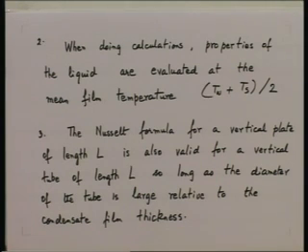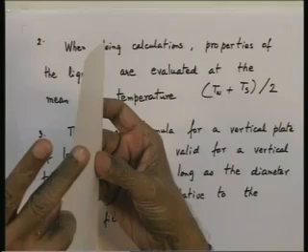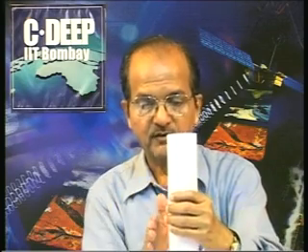And this is very easily seen. Suppose I take, just look at this now, I have this as a vertical plate here, all right. Now, if I were to fold this into a vertical tube, condensation will take place all the way on the outside of this tube, you understand. Now, so long as the film thickness, the condensate that is falling on the outside, is small relative to the diameter, obviously, the result for a vertical plate is going to be valid for a vertical tube.